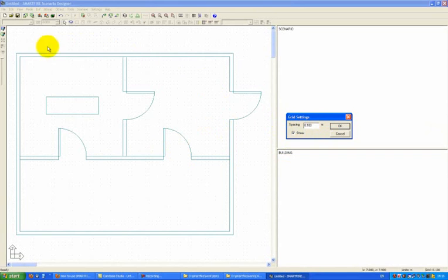If it's a small geometry like this, you can probably get away with a fairly fine spacing of about 0.1, like 10 centimeters. But if you have a very large scale geometry, a whole building for example, you may need to go to 0.2 or 0.4 meters, or in extreme cases even larger. Remember, this is only setting the accuracy of the snap grid in this tool. You can still have smaller cells than that in the meshing, and you can still edit the objects of real importance and change their positions if you need to.